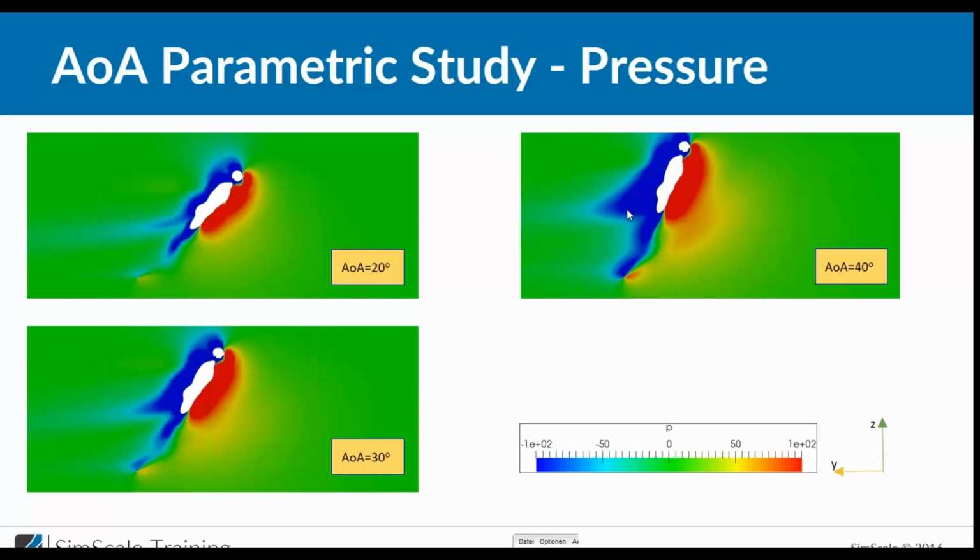And basically you can see what is generating drag and lift. So we have this red to orange high pressure region, which is on the chest, or starting from the chest of the ski jumper, and we also have this blue low pressure region. And as you can imagine, this pressure difference between blue and red will result in a force, which in this case is generating drag and lift.